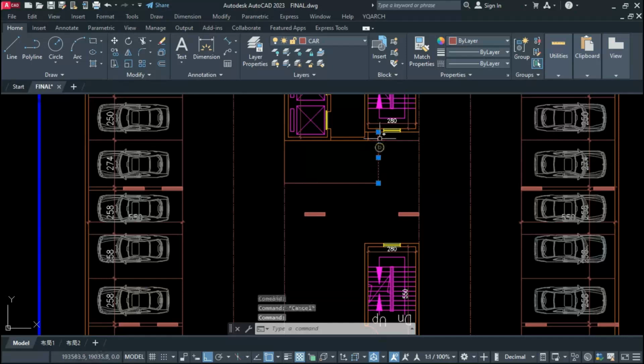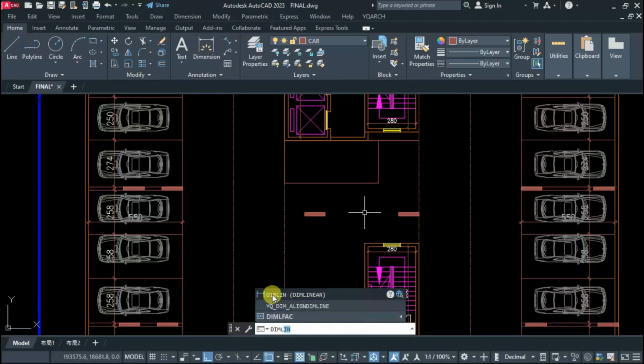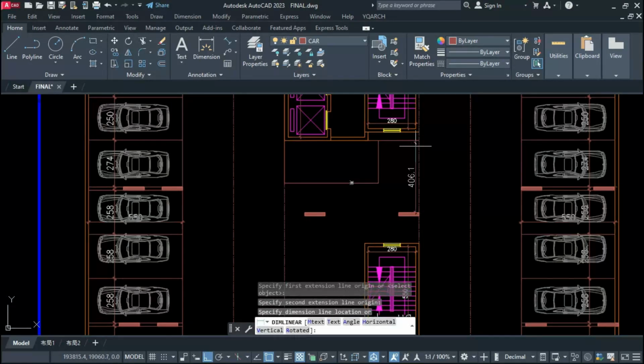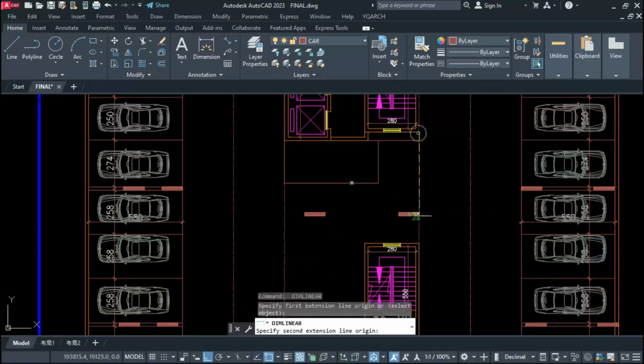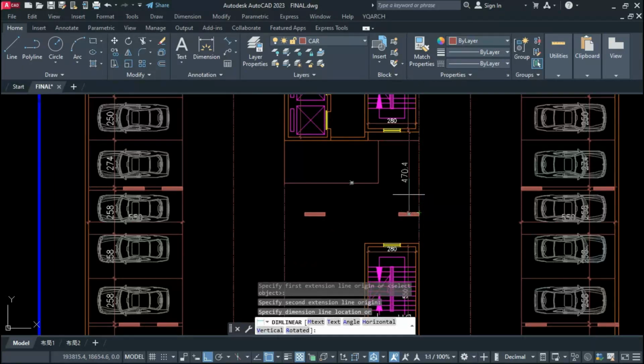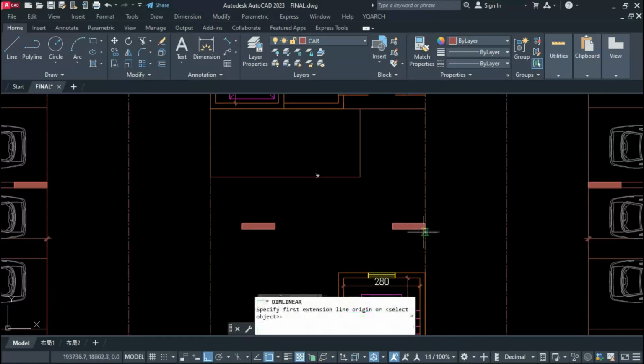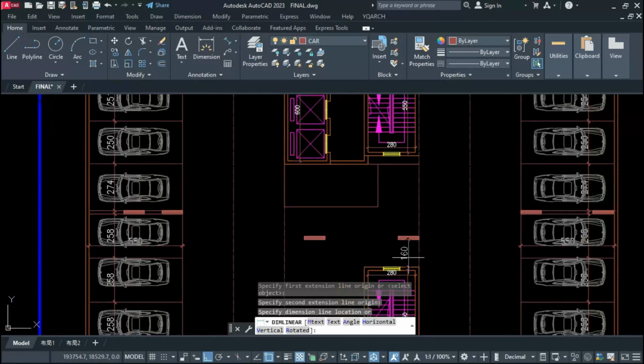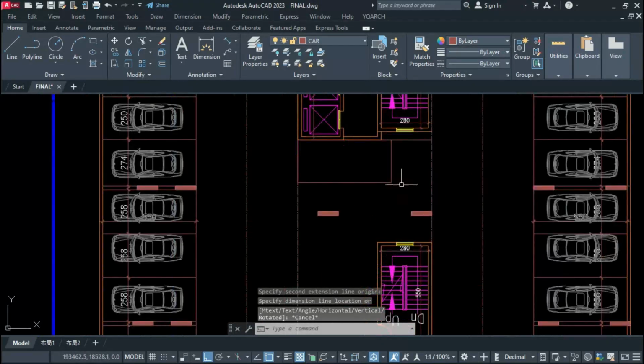If you see here, we are getting a column here. So it is not possible to place parking here. So in this case, what will we do? We will readjust our column. Okay. Because here is the possibility to readjust, because we are getting a shear wall. So we are getting a wider span here, but we can arrange because we have two shear walls at the staircase.